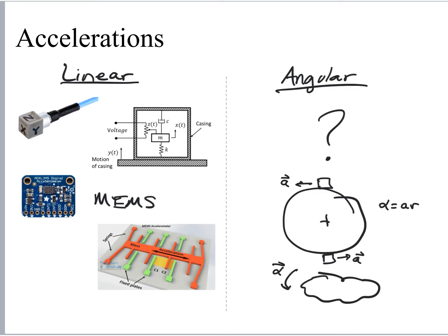So the flexible element you see in the orange here. By having a large body, it has its own mass. And by having relatively thin sections that attach to anchor points at the edges, it creates some sort of flexibility. And so you get the mass and the spring all in one.